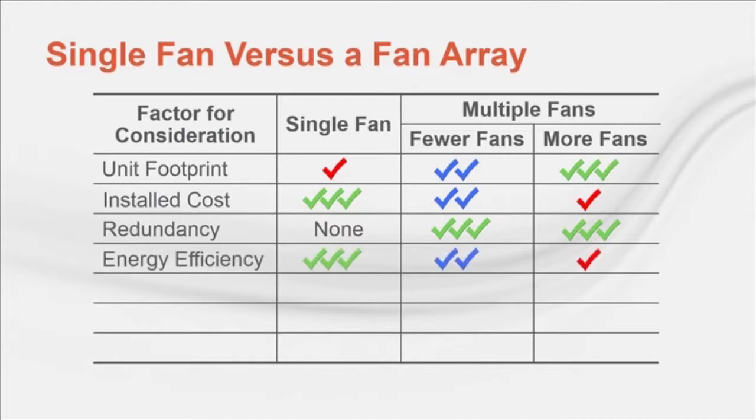Using a single fan will typically require less power than an array with multiple fans. When a fan array is desired, using fewer, larger fans will typically require less power than using many smaller fans. Since the fans are operating at a slower speed and the larger fans are more efficient, a fewer number of fans will often have better acoustics. This isn't a certainty, however. The sound spectrum changes enough when more fans are added that a comparison of quality sound data should ultimately determine the best approach for the application.